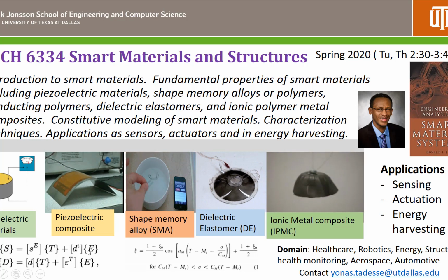So we add this term in the piezoelectric material to define the constitutive equation. And this is electric displacement, and this is stress, this is electric field, permittivity, and piezoelectric constant. So this describes the constitutive equation of piezoelectric. We'll come to this in detail in this class.